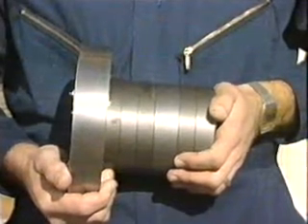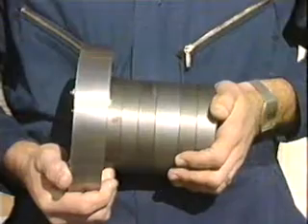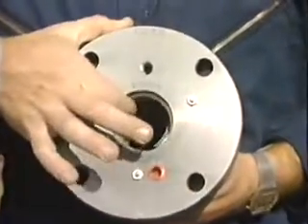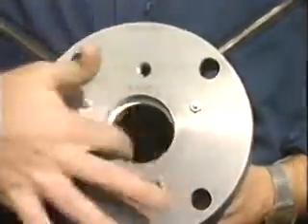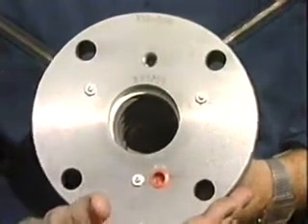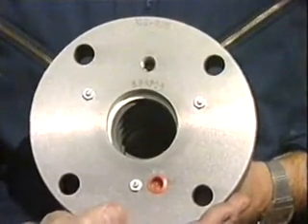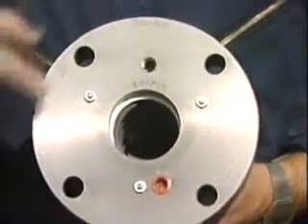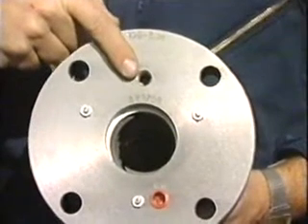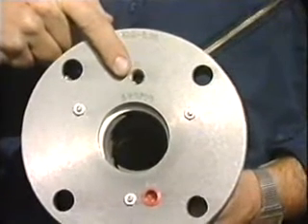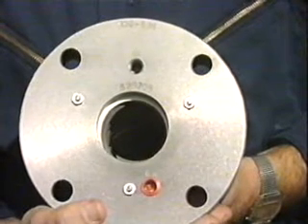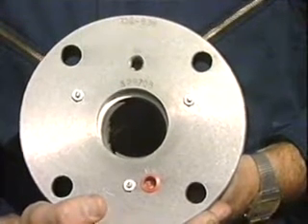Moving along now to the crank end of the cylinder, we find packing that surrounds the piston rod. Constructed of rings and cups in a cage, packing is used to prevent pressurized gas from escaping to the atmosphere, or crankcase. To reduce wear, the packing may have lubrication ports, or be constructed of special materials, such as Teflon. Like the cylinder, the packing can also have cooling vents for water circulation.